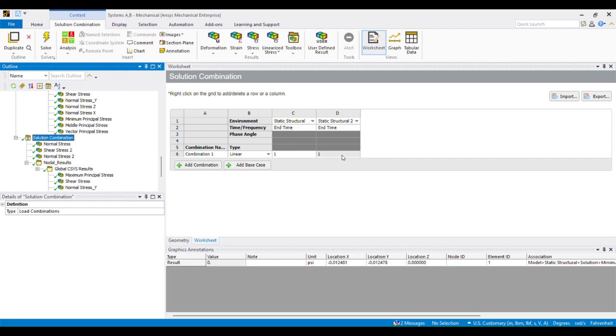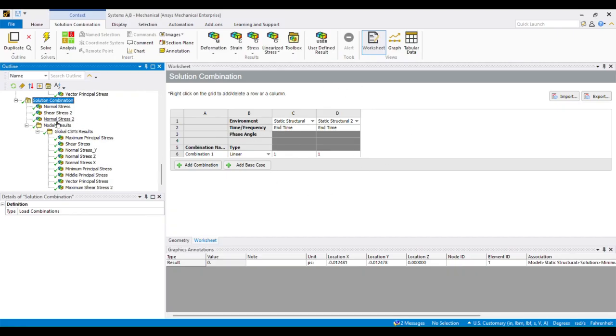Let's say you had a part that had various loadings on it over time, and you wanted to calculate those individual stress states. Rather than run ANSYS for every one of those, you can calculate unit loads and then run the results by nodal superposition. So for our node, what I've done is